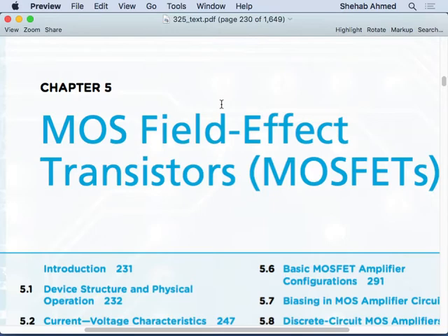With the diode, it was fine, but it was not very clear what the application was except for voltage regulation, right? For voltage regulation, it was fine. We have a voltage with ripple, and the output was voltage with less ripple, right? So we were sort of attenuating, if you wish, the input ripple by operating the diode at a certain point on the IV curve of the diode.